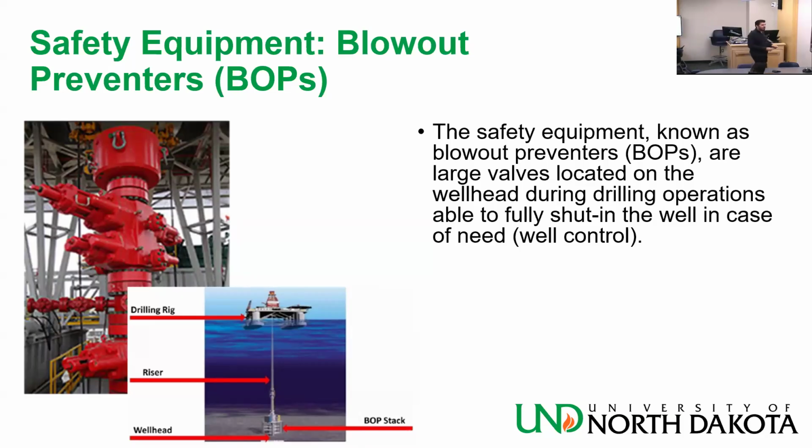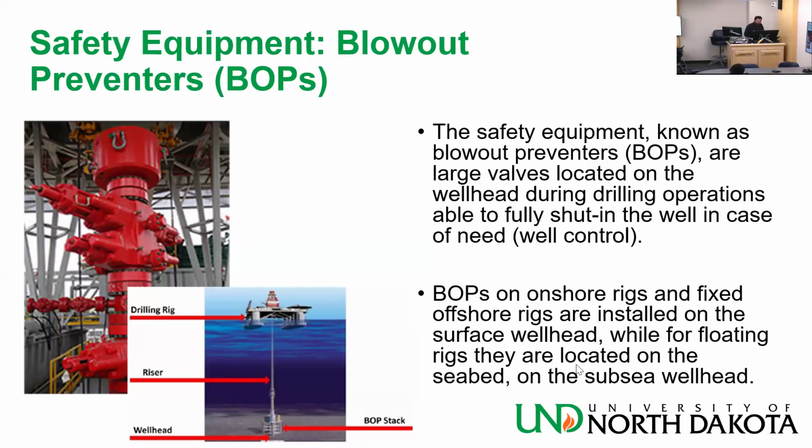The safety equipment known as the blowout preventers are large valves located on the wellhead during drilling operations, able to fully shut in the well in case of need, that is a well control situation or loss of well control. BOPs on onshore rigs and fixed offshore rigs are installed on the surface wellhead, while for floating rigs, because they are moving, you don't want to do it on the well, you want to do it on the sea floor because there is a range of motion.